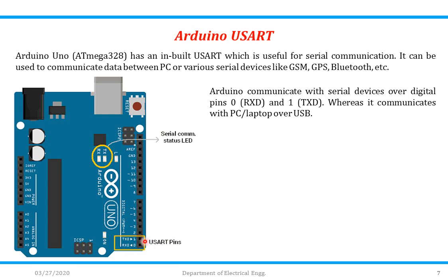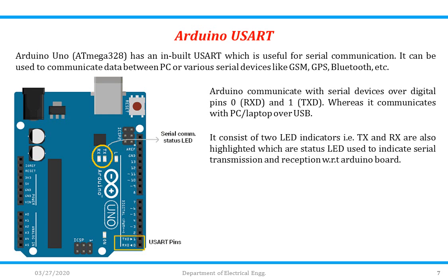This is your digital pin 1. What is written here? TXD. So Arduino communicates with serial devices over digital pins 0, that is RXD, and 1, that is TXD. Whereas it communicates with PC and laptop with the help of USB.